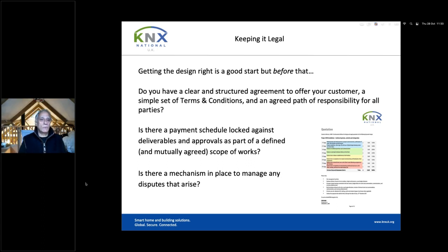It's important to issue a formal RFI, a request for information, when it's required, because again, it provides an audit trail that says we need this. If we don't have it, then there's the risk of delay, and that has an effect on everybody's bottom line. If there are any changes to the works, to the scope, it's important to issue a formal notification, which again becomes part of the audit trail and supports any price differences.